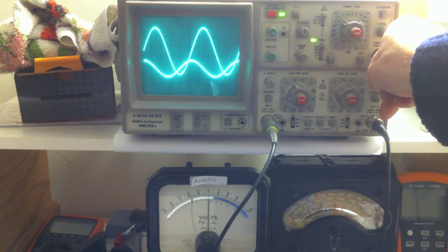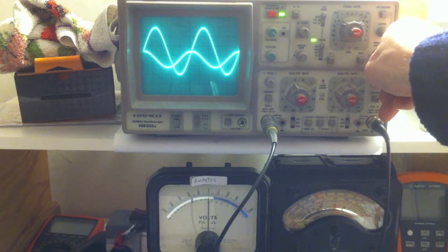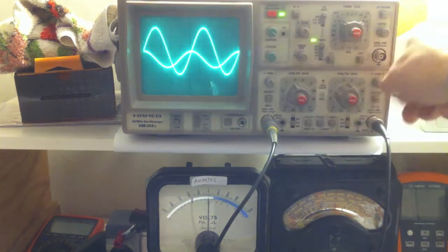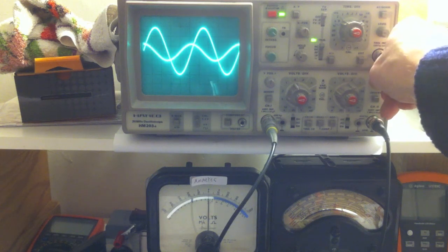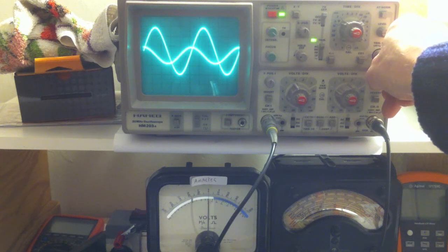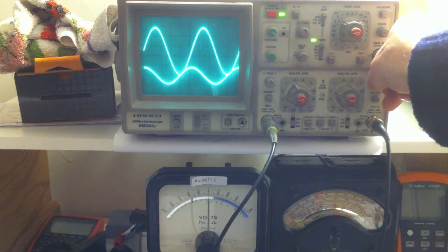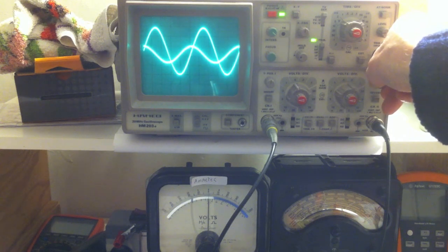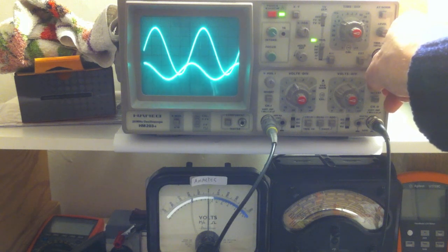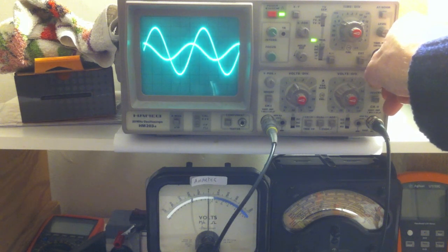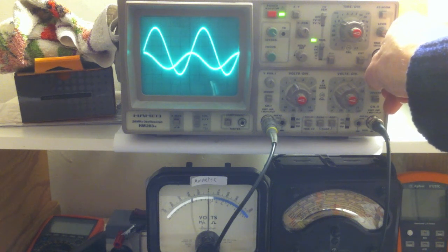So if you look at that, that is pi/2, that is 90 degrees shifted. So this one that I'm moving up and down leads the voltage by pi/2. It leads it by 90 degrees. So you can think of the voltage in as a sine wave. You could think of the voltage out as a cosine. And if you've done any calculus, you know that when you differentiate a sine, you get a cosine. So there you go.